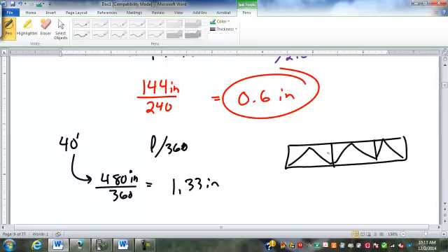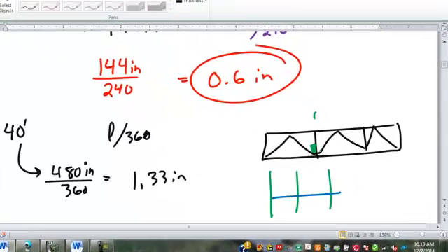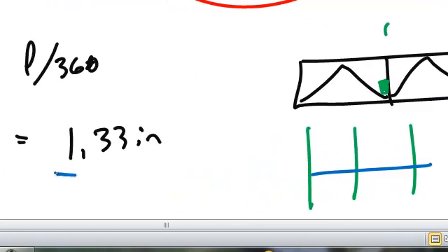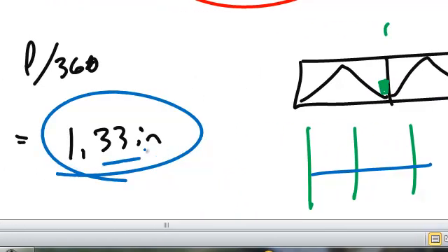They usually attach, usually in spots like this at the lower part of a vertical web, they'll attach 2x4s. They call them strong backs. So if this is your trusses from the top, those 2x4s go like this. They hold them together so that one truss cannot sag on its own. If one truss is sagging, it's allowed to go 1 1/4 inches. The other trusses beside it are going to flex and sag as well, so that it doesn't get that sudden movement right at one spot. Your floor sheeting also does a little bit to tie them together in that way, but it's still necessary to have those strong backs in there. Otherwise, it really wreaks havoc on your sheetrock down below.